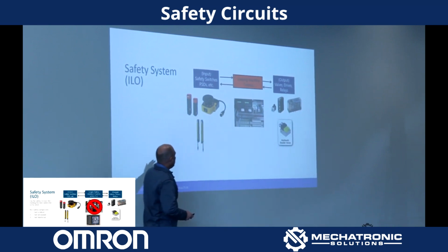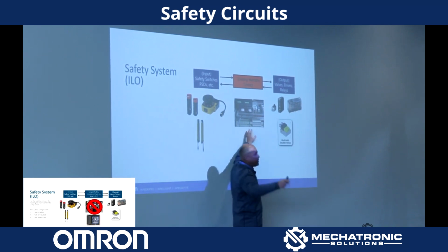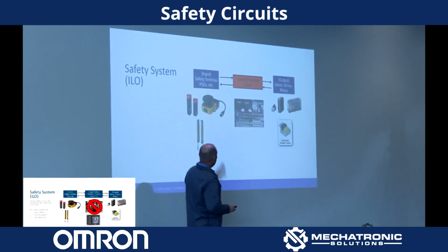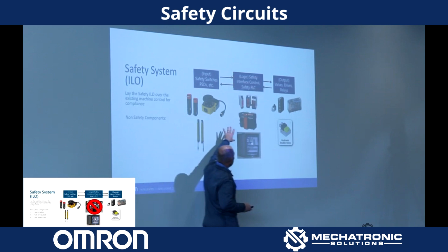So if we just tie in here, though, we talked about it, and you confirmed, because you're a controls engineer, that if I have a single relay here, I could have a complete failure that would lead to an unsafe condition. So I don't want to do that, so we'll get rid of that. And then what we do want to do is have some sort of logic control in place.